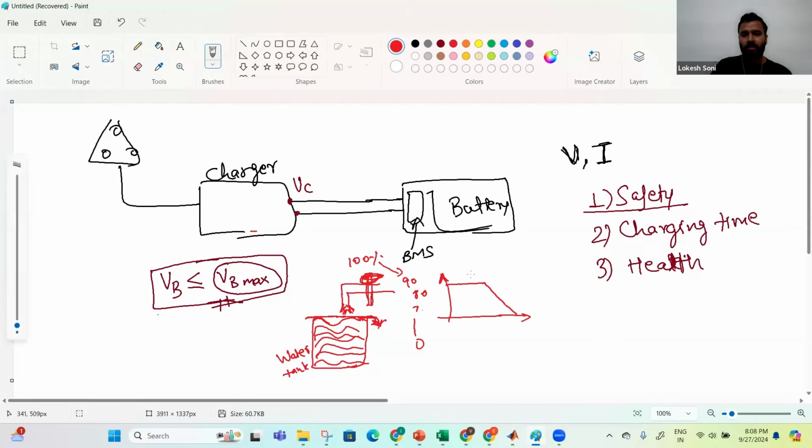So in our case, it is battery voltage. When we charge our battery, initially we pump a good amount of current, and that is our CC value, constant current, considering the health of the battery. We decide some current value, and we give that constant current continuously. So the battery charges quickly, but once this criteria is met, we go into safety mode.